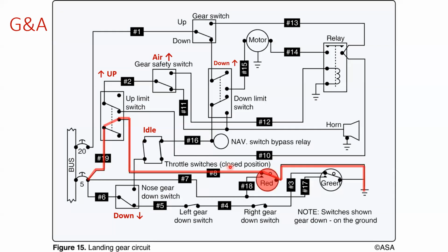And then on some of the big aircraft I've worked on and seen, the indication for landing gear when they're in cruise flight, they don't need to know it. It just actually disappears. And then when they need to know, like they reduce airspeed and they get to lower altitudes, such as below 2,500 feet, then the indication comes back up to show which position it's in.